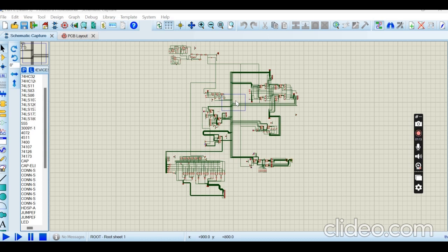We also use a program counter for containing the address and executing the next instruction. Since we are using 6-bit and the RAM is 8 by 6, the counter will be counting from 000 to 111.